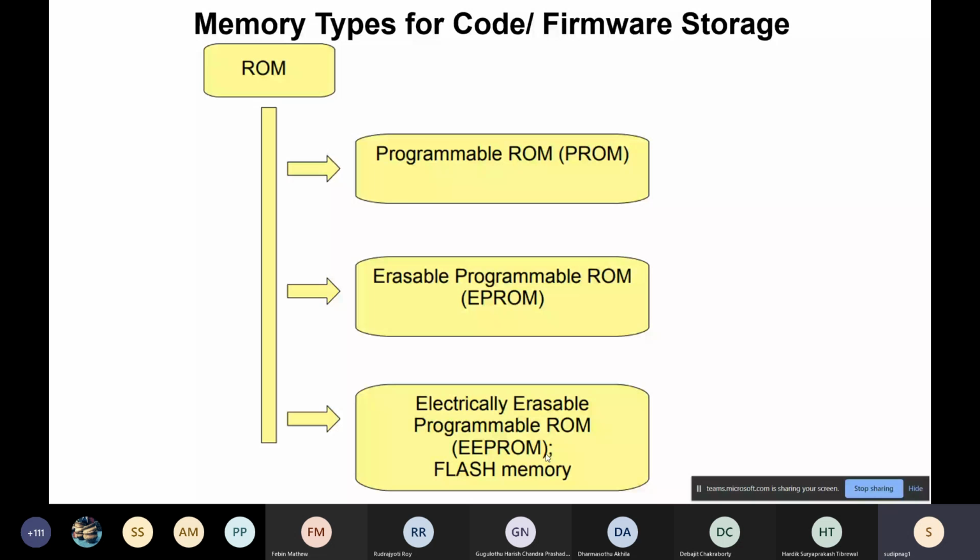Okay, you can note down this term, endurance of a memory. Endurance means number of write, erase cycles. The endurance of flash memories is typically very large. Later on, EEPROM also advanced to more than 1 million, and flash has also advanced to more than hundreds or tens of millions these days.